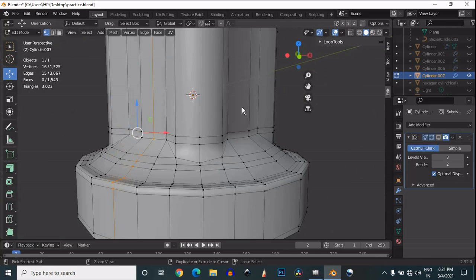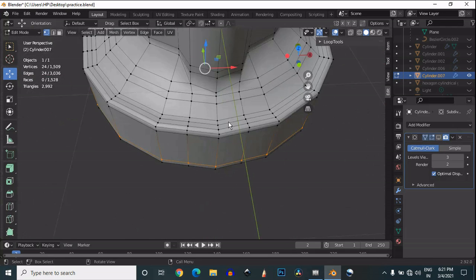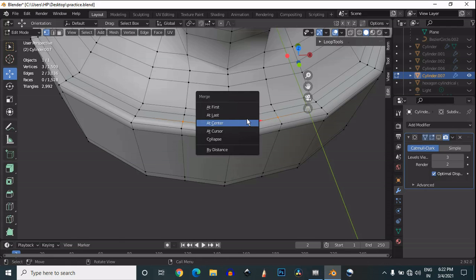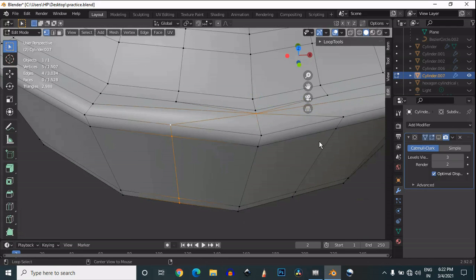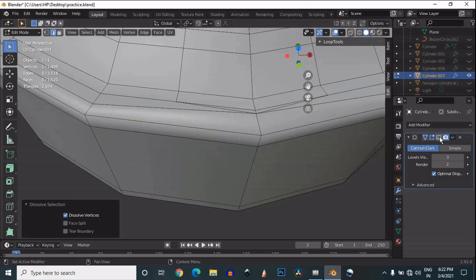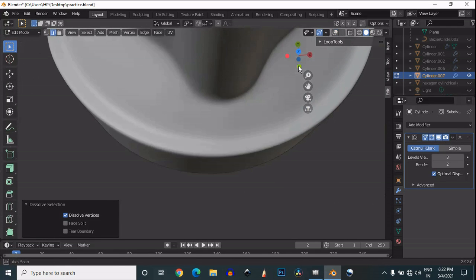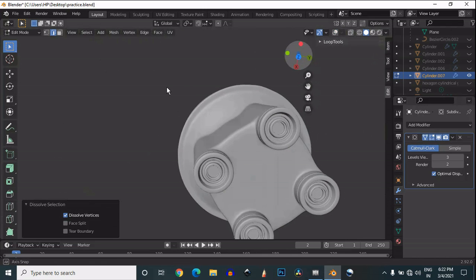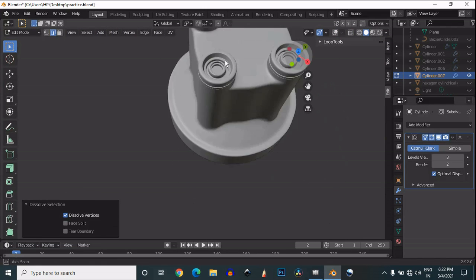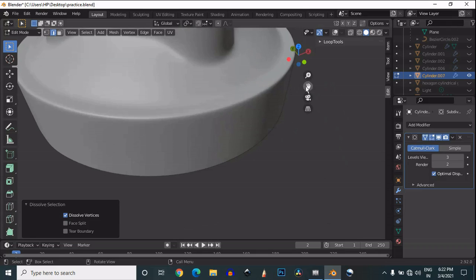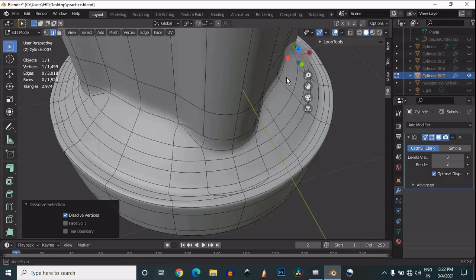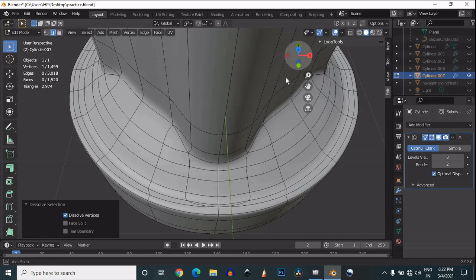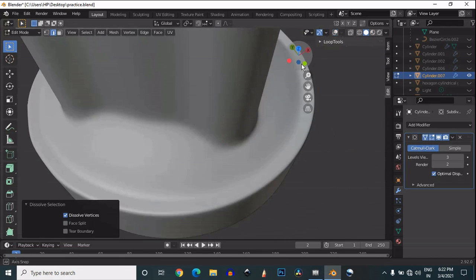You can see if I add something like these vertices, then it will break the circular path and we can break that curve. So there is only one option, which is to merge the vertices like this, welding the vertices at a single point. So this is one option. You can weld the vertices like this, and you can maintain the edge flow.